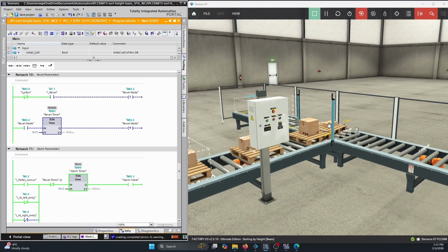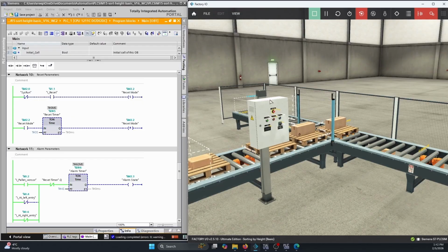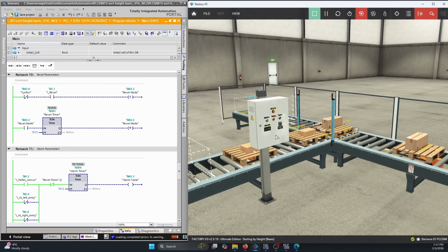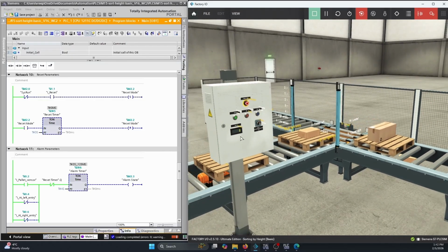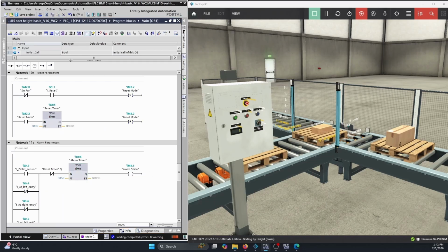So I'm going to move this guy off of the conveyor here. Okay, let's start everything up and see whether this runs now. Looks good. We're getting a count of each of the pallets that are going by. Looks like I might have to increase this to 5 seconds, eh? Because at some point it is tripping off my alarm state during normal operation.